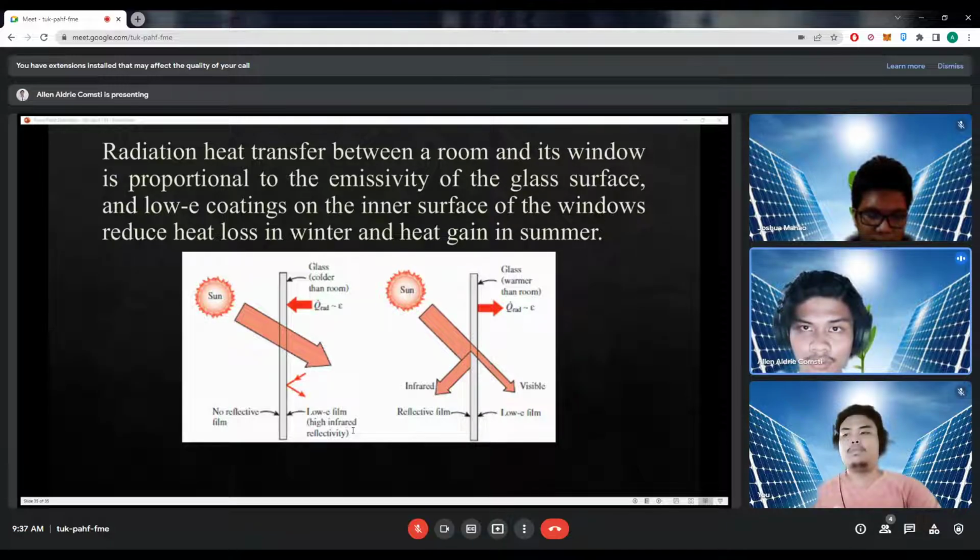Double pane windows with tinted or reflective films are commonly used in buildings with large window areas. Clear glass is preferred for showrooms since it affords maximum visibility from outside, but bronze, gray, and green colored glass are preferred in office buildings since they provide considerable privacy while reducing glare.